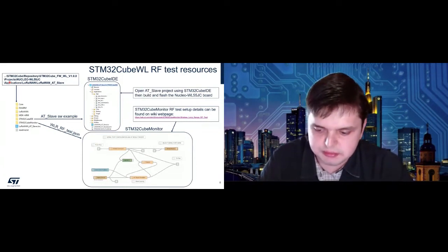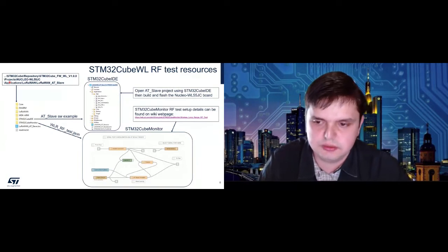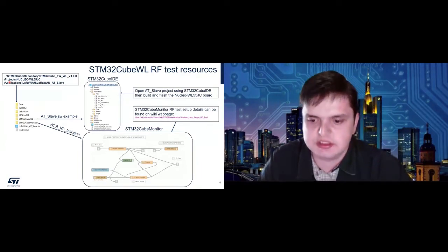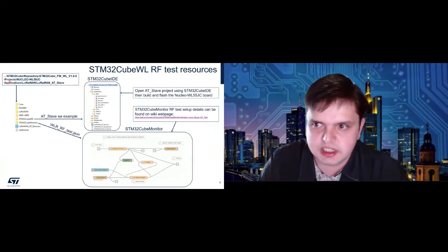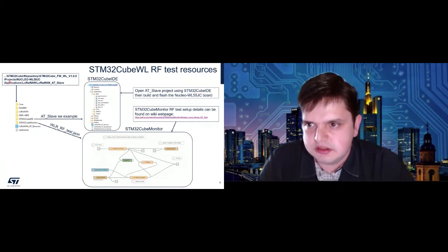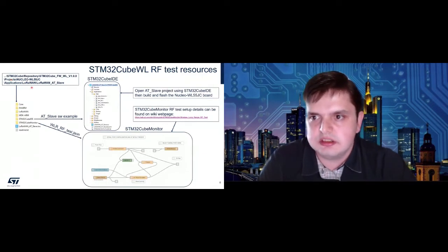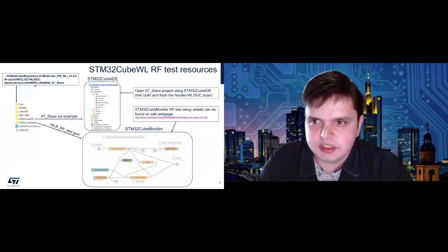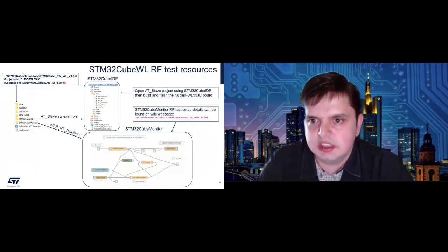Examples are very simple. Examples are called the folder, and within these folders, there are very simple applications to toggle an LED or to communicate over I2C, and applications contain usually some middleware. So in our case, it's the LoRaWAN, and for the use case of the LoRaWAN stack, we have the LoRaWAN AT slave located there.